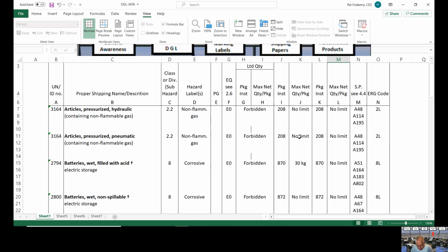Risk to occupants is indicated by the drill letters. Spill or leak, use 100% oxygen. It's telling them how to comply with this. Maintain minimum ventilation. Firefighting measures: all agents according to availability, use fire standard. Basically saying if something ignites, use your normal measures, nothing special needs to be used. But an additional consideration is possible abrupt loss of pressurization. If it's near anything that could cause that, the pressure in the aircraft could change, so you should be aware of that.